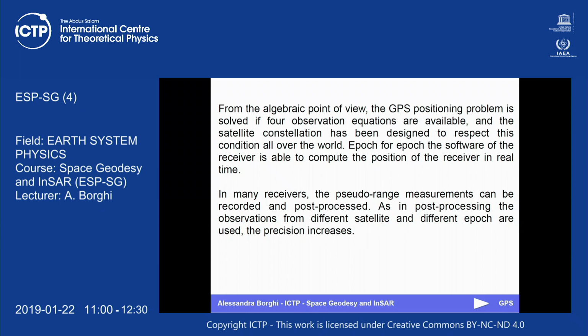If you don't want real-time positioning but post-processing positioning, it's okay, because for instance you collect data for a geological application to geolocalize your survey. Probably you can come back to your office and process more data. You say, okay, this is the point where I found the free face of the fault, for instance. I want to know the coordinates. I can stay a few minutes with my GPS, collect data, and I use more observations to compute my position, that is given again from the unknown parameters plus this correction.